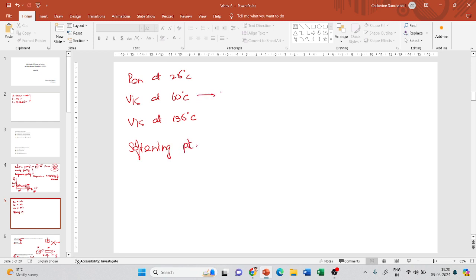And out of this, only this has a range. All these will be mentioned as either a minimum limit or a maximum limit. You have to check whether your bitumen satisfies all these parameters to be graded as VG10, VG20, VG30 or VG40 bitumen.